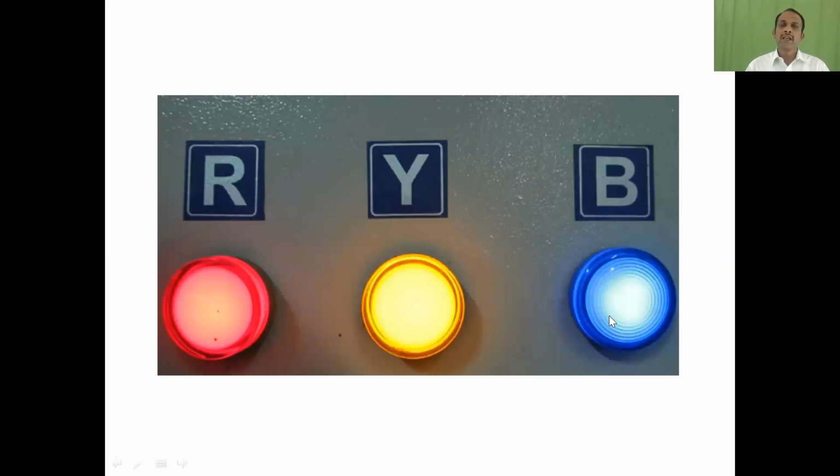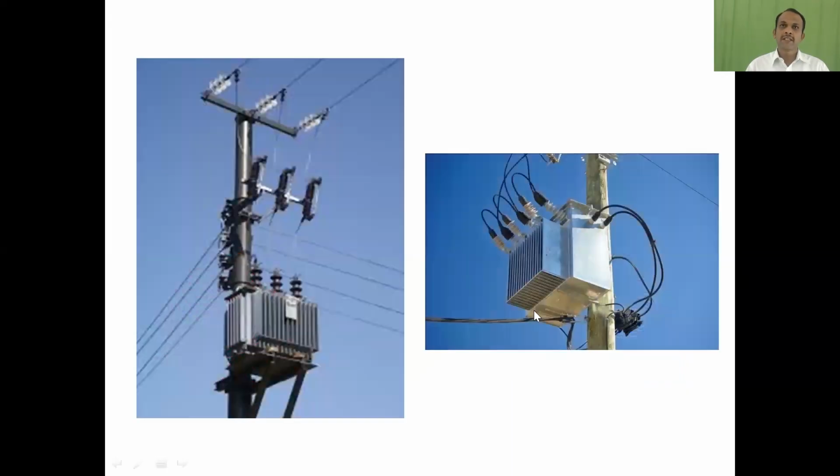There are going to be three-phase waveforms, voltage waveforms, current waveforms, and load present. Basically, it is represented like this, which means that they are operating with a three-phase supply. So this is a common site for everyone, occurring near a colony or an apartment or some villa. These transformers are called distribution transformers, where they get 11 kilovolts as the input supply and step it down to 400 volts, all in three phase. This 400 volts is divided into each phase, and we get 230 volts.